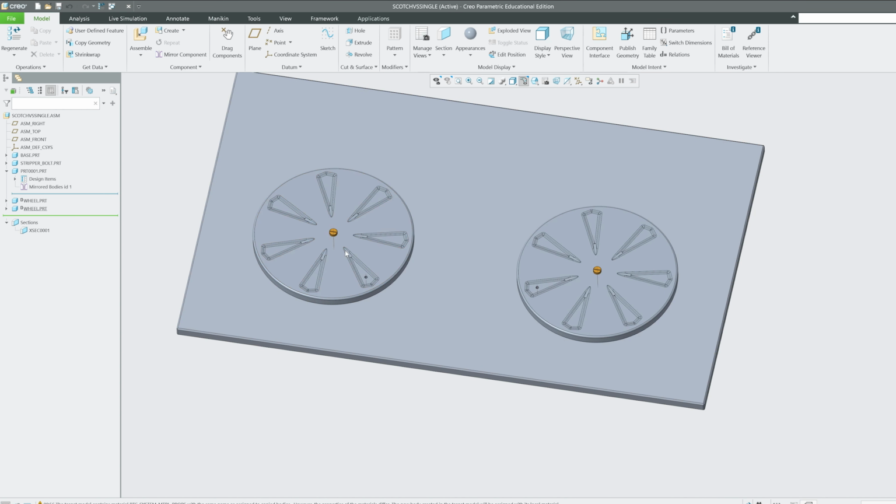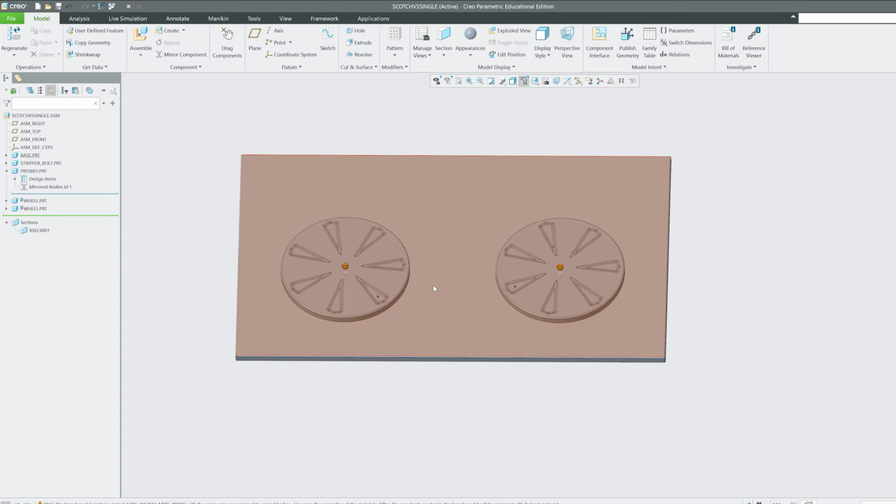So for those who are wondering how I am simulating this kinematic analysis, you need to press Control and Alt, and then use proper joints and connections the way we used here, pin joint, and simply press your left mouse button, and then you can play with your connection.